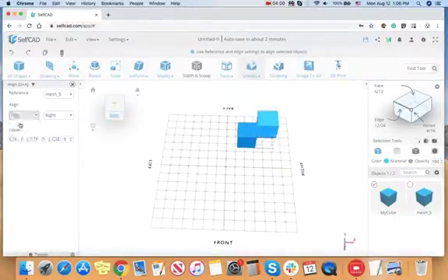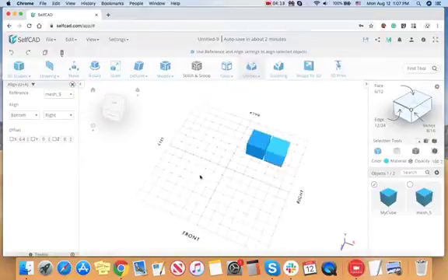If I choose top, for example, it will go higher, or center, middle will go in the center. So I choose the bottom on the right side. But what if I want to have a distance now? So I have to look at which axis I'm dealing with. In this case, I'm dealing with the x-axis. So I'm going to add 6.4. 6.4, and you perfectly aligned it.